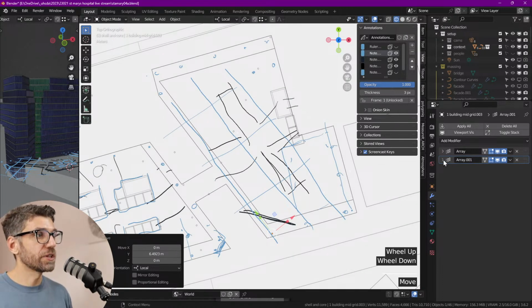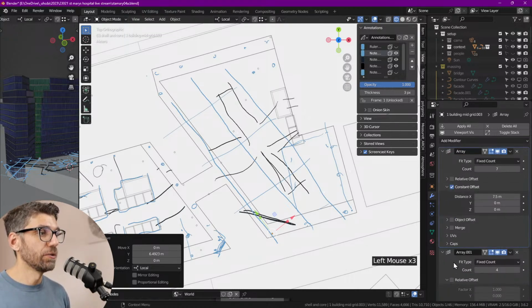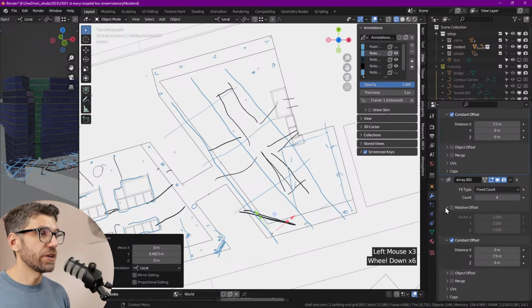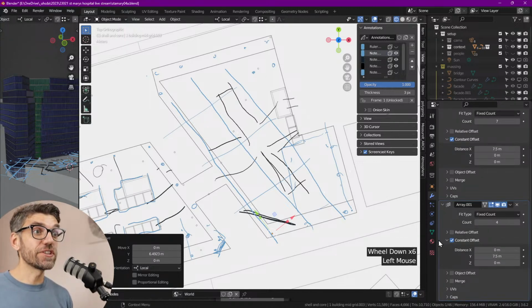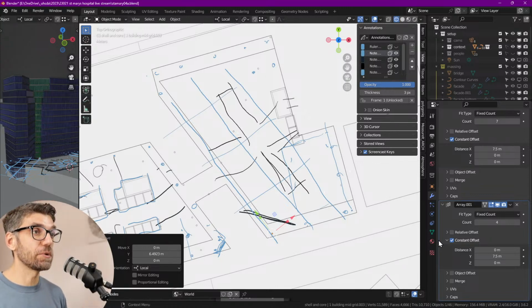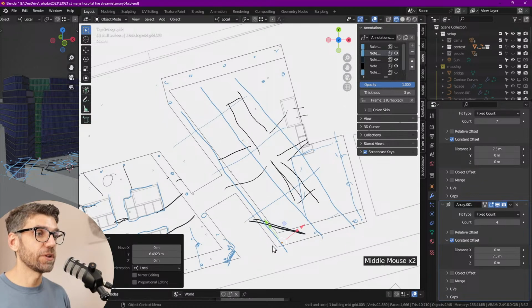So what are we using here? Let's just double check. 7.5 meters. So that's a very comfortable grid size. It's not too small. It's not too large. It's comfortable. What does that mean? It's fairly efficient and fairly cheap, meaning the span members, the beams between the columns, don't need to be too large, too heavy. So it's a bit more of an efficient structure in that respect. We can always go a little bit wider if we want to, but I think it seems to work pretty well for us here. So let's increase the number of members here.